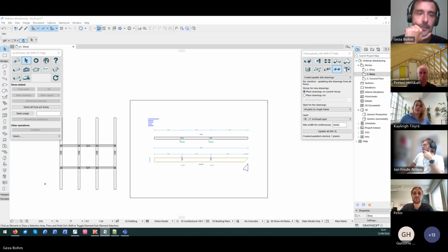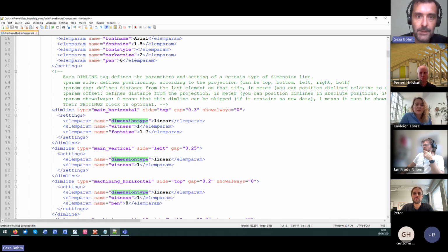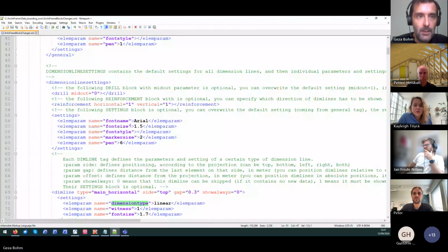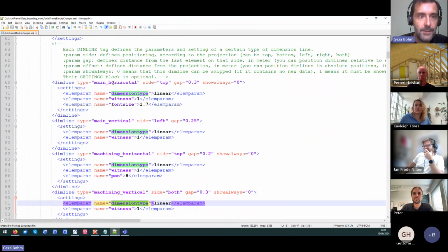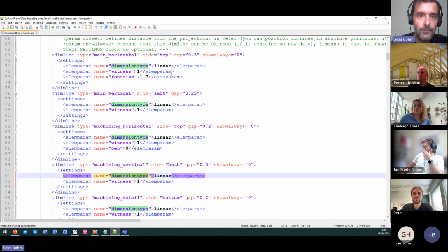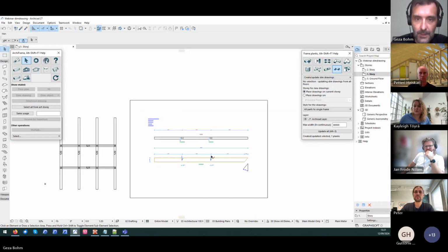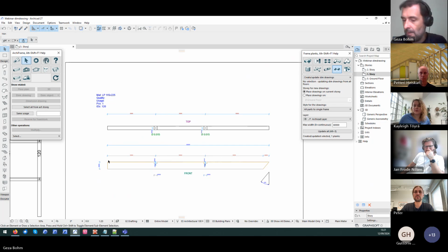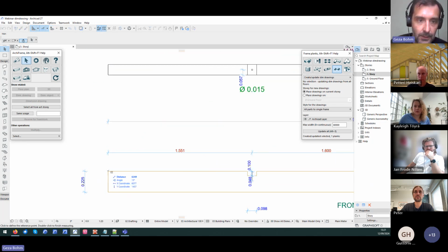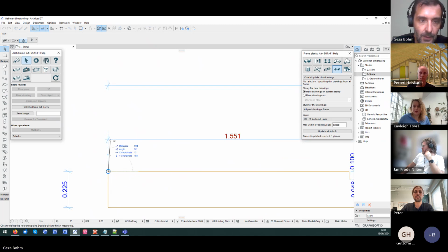The next topic will be about the sizes and more about numbers. So this dim line has a distance from the projection itself. Let's check. Now it seems great. We have this nice measurement tool in ArchiCAD. So from this corner, I go here and I see that it's 200 millimeters away, and it's a bit more than 500 millimeters. It's because the text is there on the top.